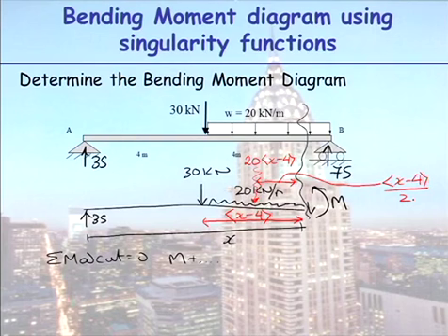So it's saying I'm going to teach you more than free body diagrams and equilibrium. What are we just doing now? Free body diagrams and equilibrium again. You can't get away from them. There are x's in there now, but x minus 6. Why 6? No, because this distance is x, see? x now represents anything between 0 and 8. Because we're using singularity functions, we're going to come up with one expression valid for the whole beam.